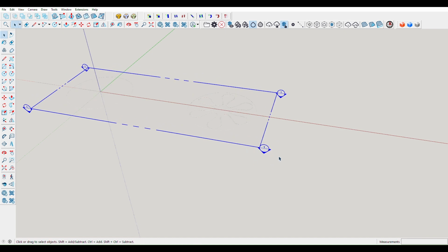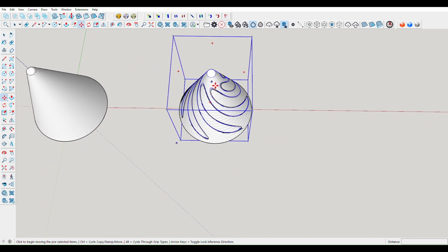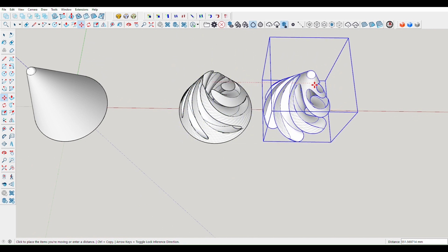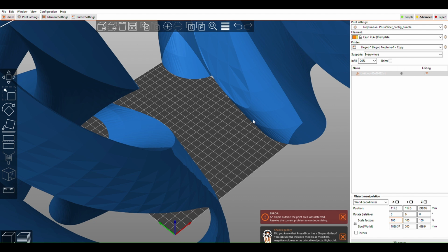Now obviously you can delete this and take this off to your 3D printer, set it up, export it. Let's go ahead and do that. Okay, so open up your slicer of choice. I'm using Prusa Slicer, and what you can now do is import your model that you've made. Now obviously when I originally started this, I said I was drawing this much larger, and I'll scale it down by a factor of 10.